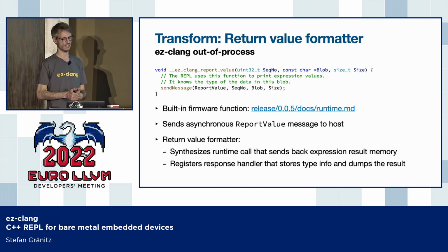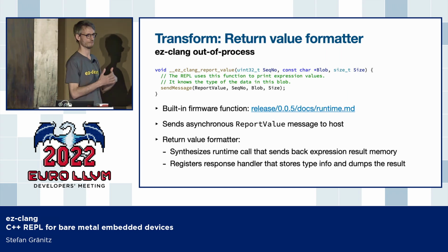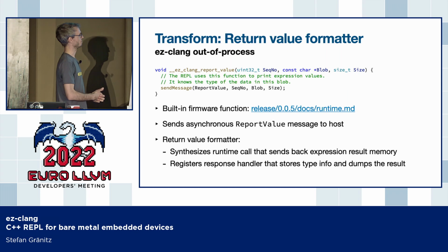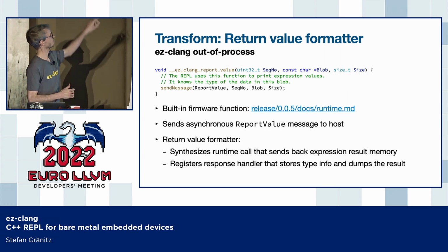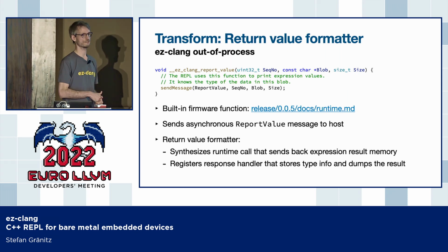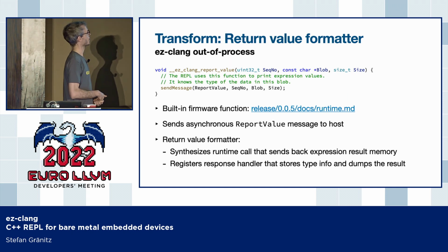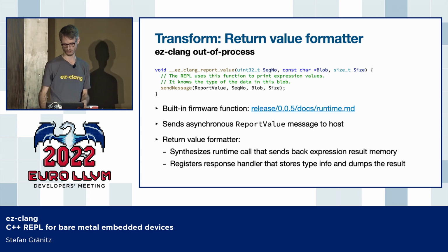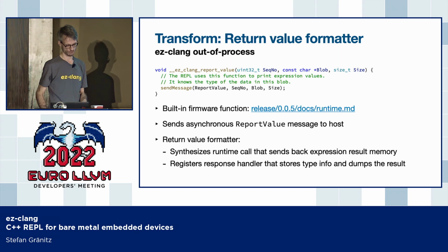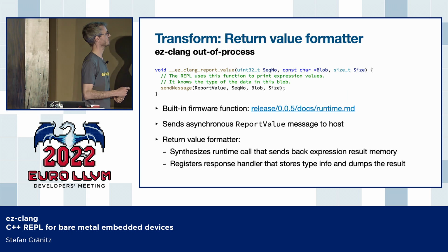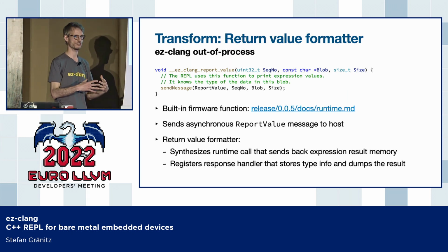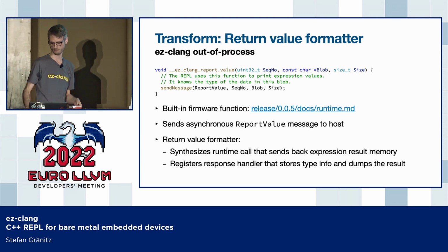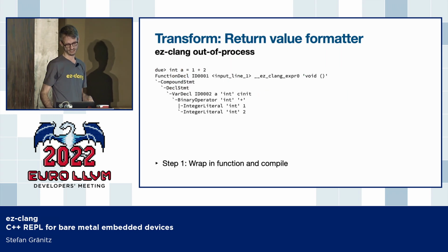Instead of synthesizing a runtime call to a print value function directly, we will call this function, which is a built-in firmware function on the device. And it will take care of sending a message back to the host, and we just have to provide the correct values for it. What we also have to do is register a response handler on the host so that there is someone who takes this message and combines it with the type information for dumping. And in detail, it looks like that.